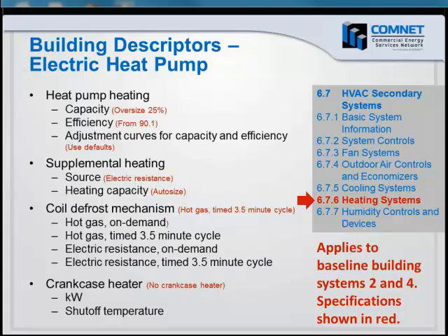Well, we've gotten questions because some of the software out there does not accommodate that sort of control, and it's an either or. Oh, I see. The compressor or the electric resistance heat, and then also down to what temperature is the compressor effective? The software I'm familiar with, I think it runs the compressor, even though it's not meeting full load, and the supplemental heat then comes on to make up for the difference. So I guess maybe since the subcommittee's in the process of writing this interpretation, it might make sense to look at what they come up with and try to incorporate it. I don't think we actually addressed whether the compressor is integrated or non-integrated with the supplemental heat. And that's really the issue here.